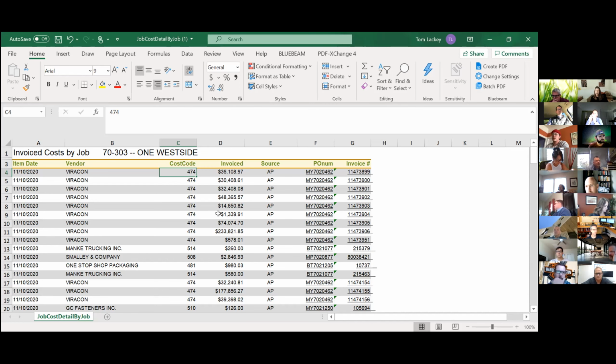And one other thing: when you're going through here and cleaning it up a little bit, sorting it by cost code, you're going to have some items that possibly deliver directly to the field. So you would want to wipe those out as well. If you had your embeds going straight to the job site, on your G703 you're going to bill that as job site and not stored. So you could bill 100% whether you have an invoice or not.